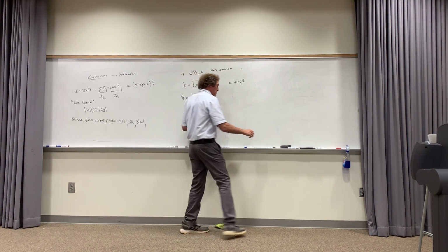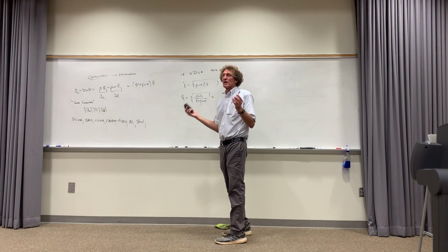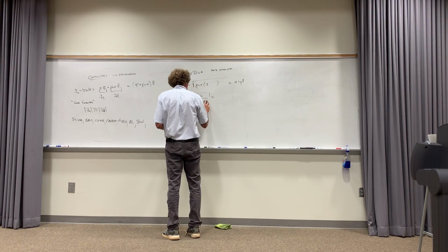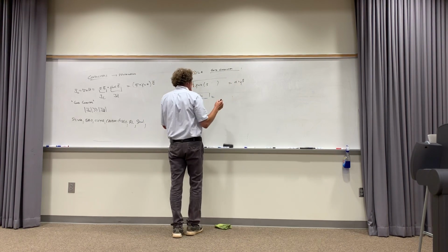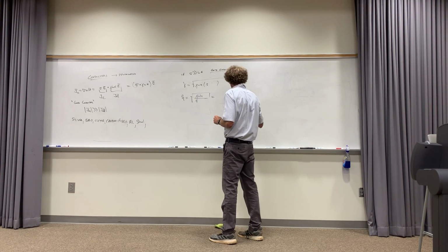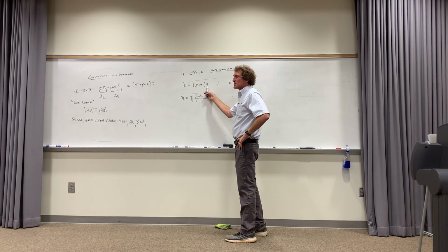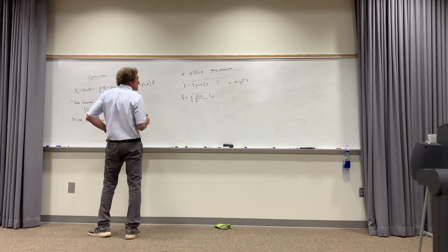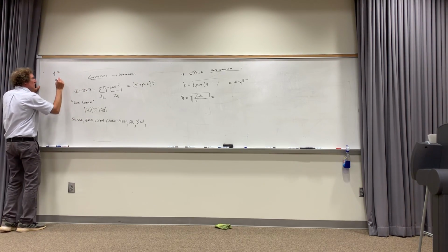So what I'm going to do is make it a really good conductor. This is an approximation. I'm going to get rid of omega epsilon because it's much, much, much smaller than sigma for a good conductor. So if I get rid of that, now I have this, don't I, class? And this would be for good conductors. This would be the equations. Now take a look at the top one first. I have the square root of J omega mu sigma, right? I want you to note one thing about the square root of j, because it's important to note this. When I have j, really, that's what?